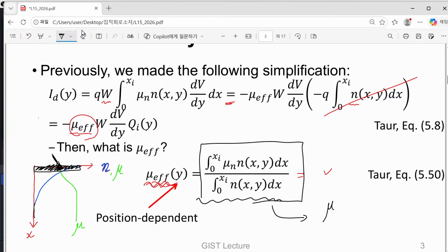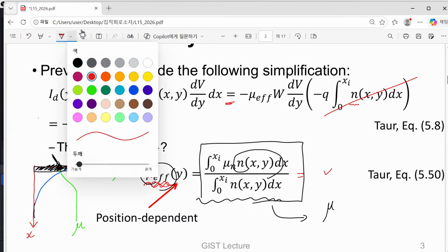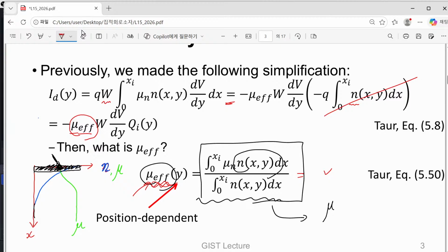We take a weighting factor that gives strong preference to a highly populated position. So are you all with me? In this case, we can easily understand the electron mobility in deep substrate doesn't matter. It doesn't play any role in our effective mobility calculation. Only the place where most electrons are found is important, and that is just within a few nanometers from the silicon and silicon dioxide interface.